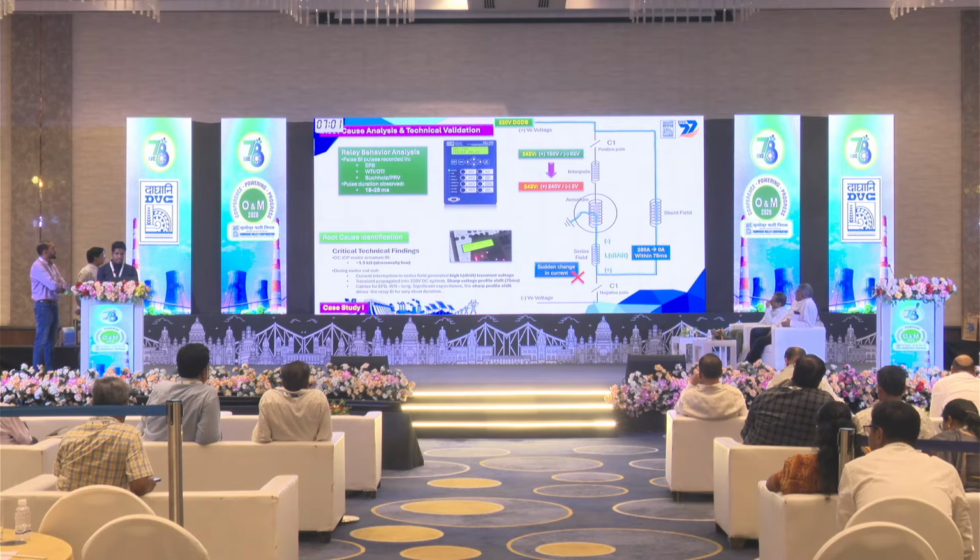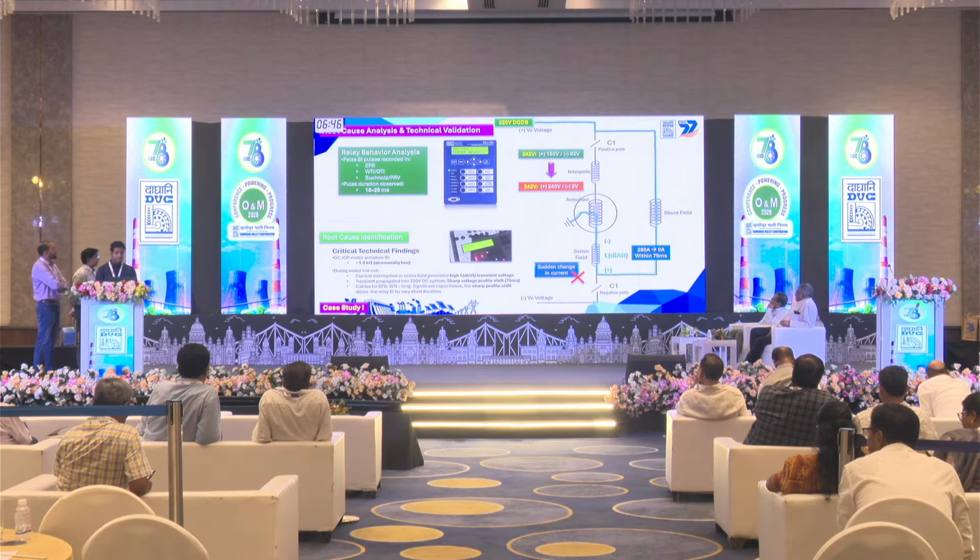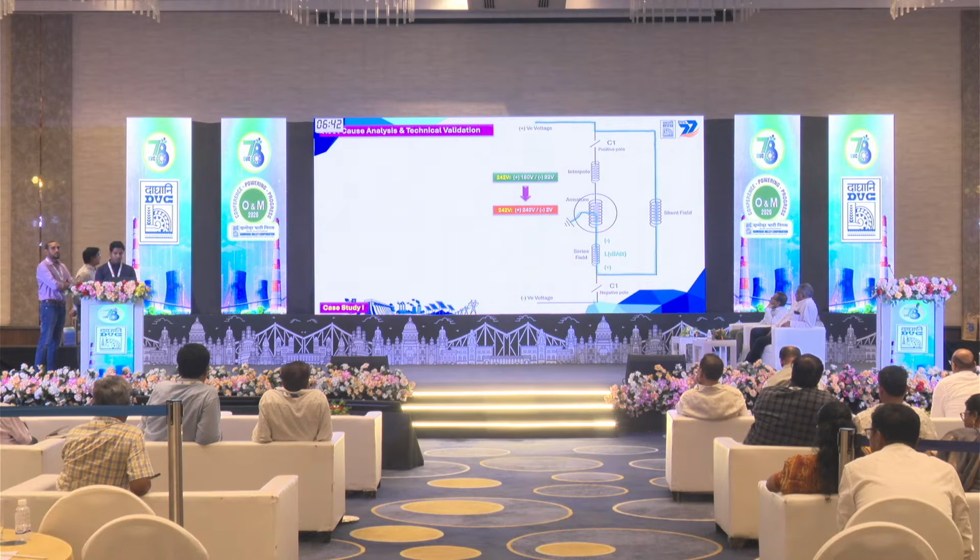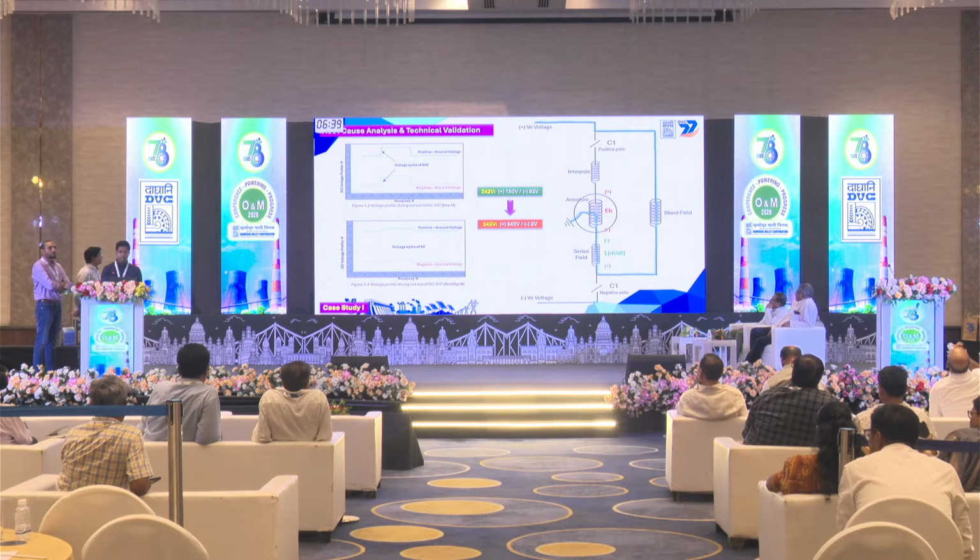And it creates a sharp voltage profile shift with respect to ground within 75 milliseconds. As we know, the EPB and WTI cables are long control cables. They have significant capacitance. So this sharp profile shift drives the relay binary inputs for a short duration, and due to that, tripping occurred. After that, to validate our intuition, we did a MATLAB simulation, and we modeled 2 motors, one with low IR value, one with high, healthy IR value. And we found our simulation result as per our field findings.